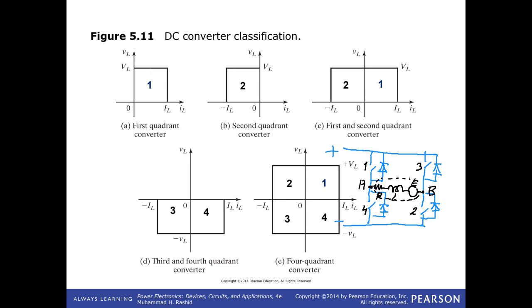Now that's the brief starting point. So these are the quadrants. If current is positive and the voltage of the load terminals is positive, it's the first quadrant. Power is positive. If current is negative here in the third quadrant, and the voltage is negative, negative multiplied by negative, power is positive. So this reflects the reverse direction of the electric motor.